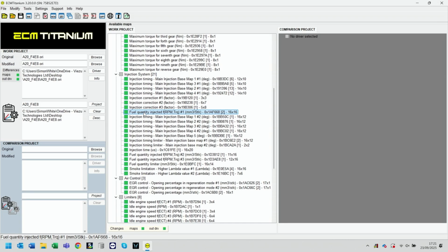Do we have the ignition for that? So that's the start of injection angle. Do we have the rail pressure? Do we have the turbo pressure for that? Does our fuel, our air, and our diesel equivalent of spark, our start of injection angle, do they all support that higher amount of torque and fuel quantity? Are they going to run out of numbers if you get into that territory? Exactly, yes. Okay, makes sense.